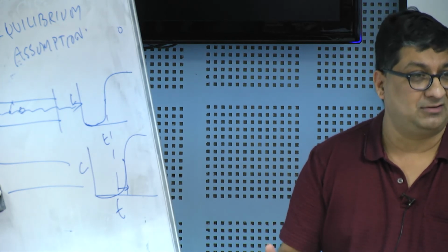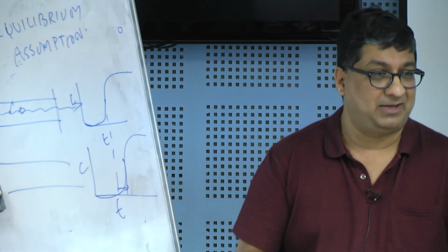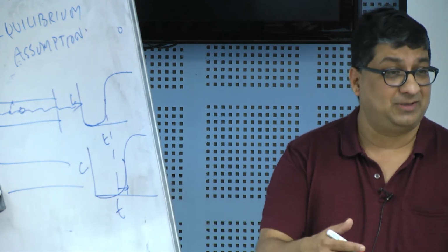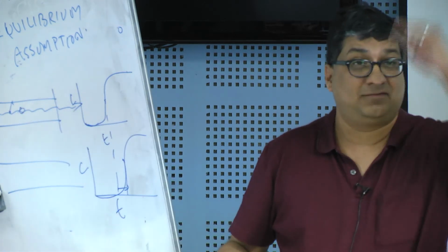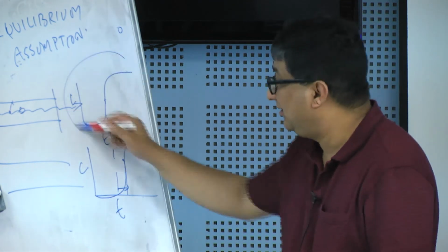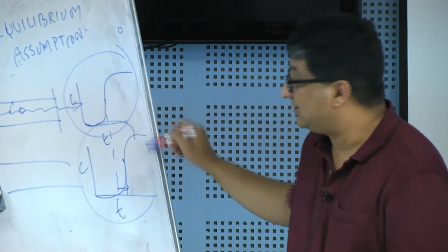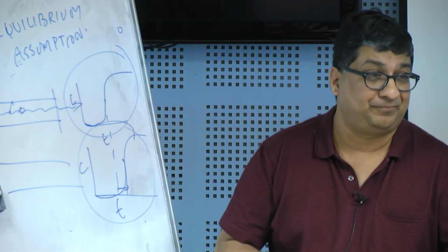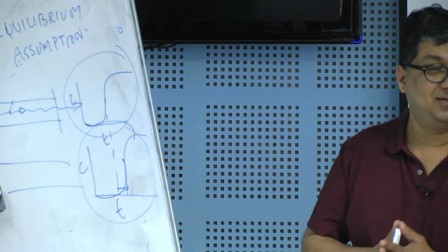It tends to retard, because the path is much more tortuous than a straight path. If I have mass transfer limitation, it means that this water is moving very fast, so there is not enough time for it to go and adsorb. So my breakthrough curve will look more like this, more like a conservative solute than it would for a retarded solute. You are saying the second phase, if you want to remove the contaminant, will again shift like that?